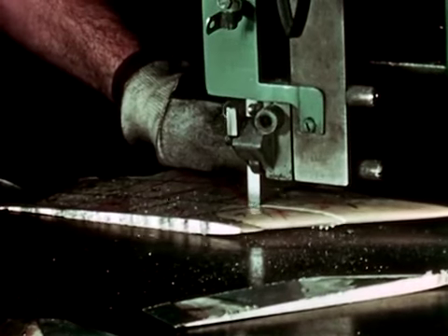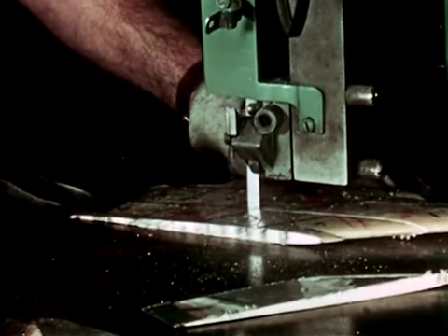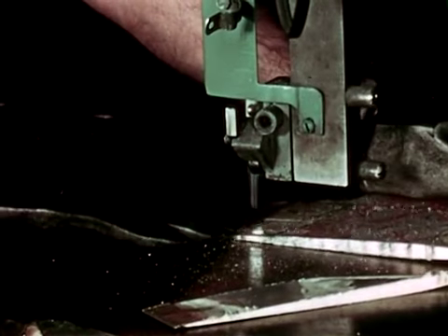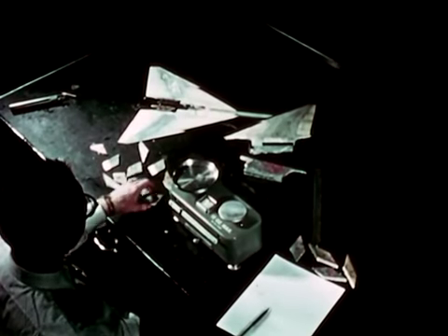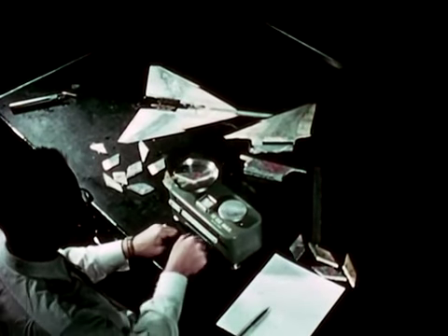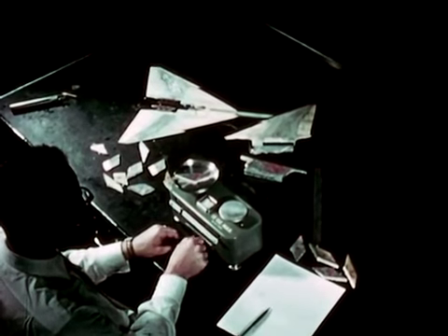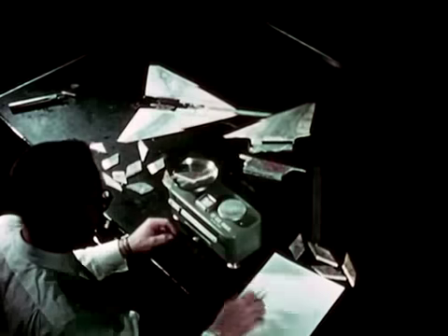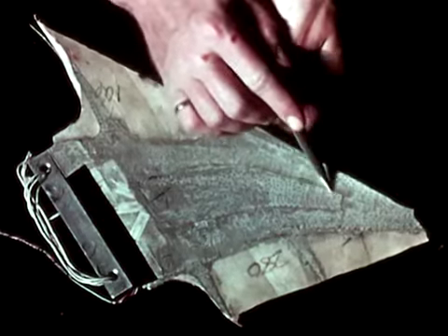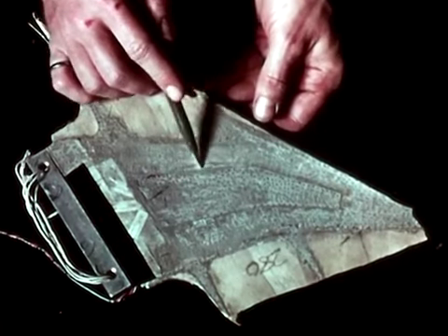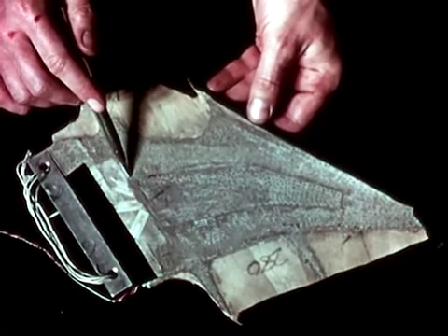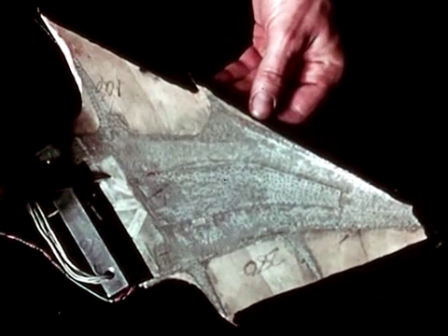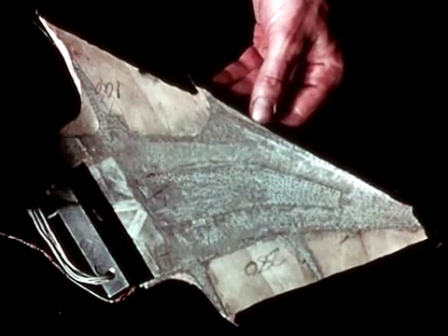A typical model was then cut into several segments. These were next weighed to check that the model's mass distribution was correct. Some models had extra skin to alter the frequency ratios in order to fully explore the flutter boundary. Strain gauges were used to record wing bending and torsion.